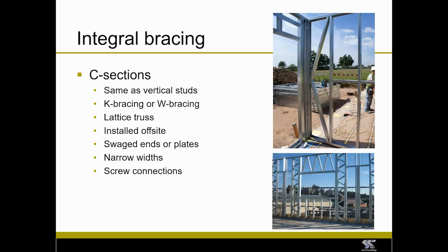That often causes a slight rise in the surface of the wall panel at those connection zones, so can make fitting boards a little bit more difficult. But if the right screws and that sort of thing are used, then it's not too much of a challenge, and you may have resilient bars and things like that to offset the boards from the wall anyway.